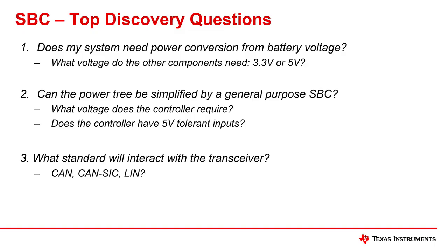The answer to question 1 should always be yes. All SBCs include an LDO to take battery voltage directly and step it down for powering the internal CAN bus and other external peripherals. The SBCs have a wide input voltage range, and they can power other components with a voltage output of either 3.3 volts or 5 volts.